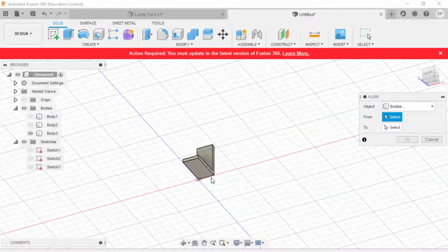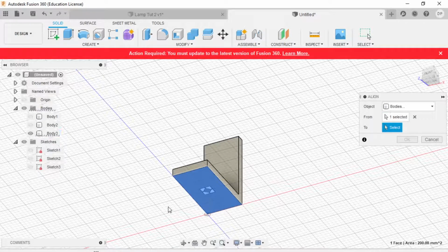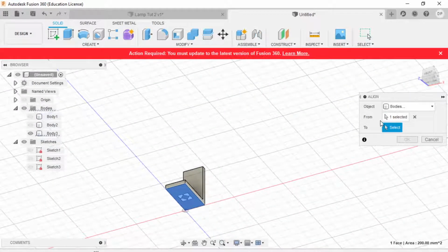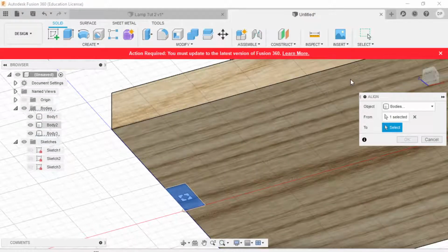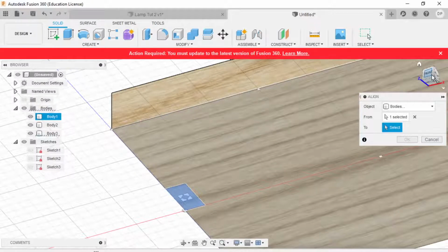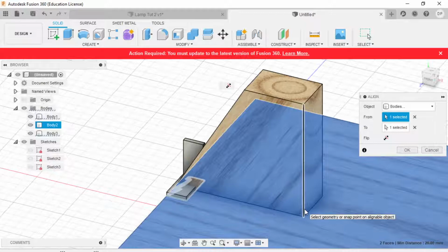This part over here, we want to move this face over here. Notice how when I bring my mouse onto the align tool and the object, you have a bunch of different locations where you can attach to. So whichever one you want to align. Let's say I want the very center of my piece to align from. That's what we're aligning the base, and we want to align it to this over here. And so now it's moved it up. It's moved it with that surface.